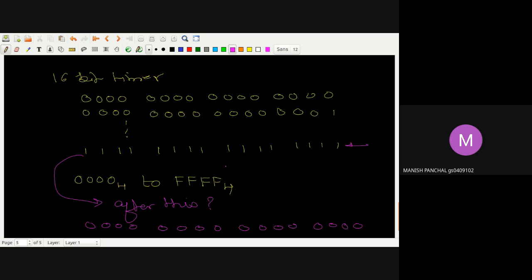Okay, so in the architecture of the 8051 microcontroller, they have designed various types of timers. The timer size is either 8-bit, 13-bit or 16-bit. When this final value is reached, they have given the provision that some flag will be set to give the information that the final value is reached. Again, the counter will run; the counter will never stop. Then you can take the decision. So they have designed the same flag.